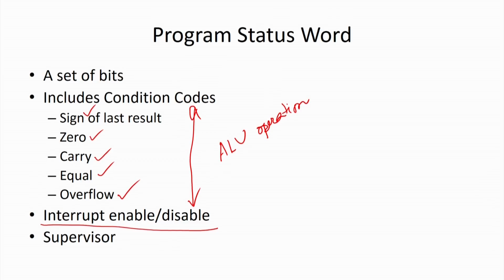What we have said is, this is the processor, say CPU, and this is a device. The device is giving an interrupt. Whenever the interrupt comes, what will the processor do? It will complete the execution of the current instruction and give service to the device, indicating it with another signal called the acknowledgement signal. Now, whenever some device interrupts, we are bound to give service to the interrupting device.